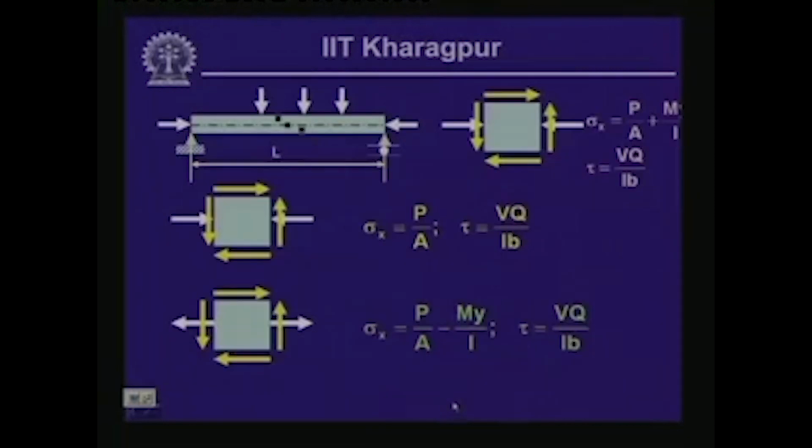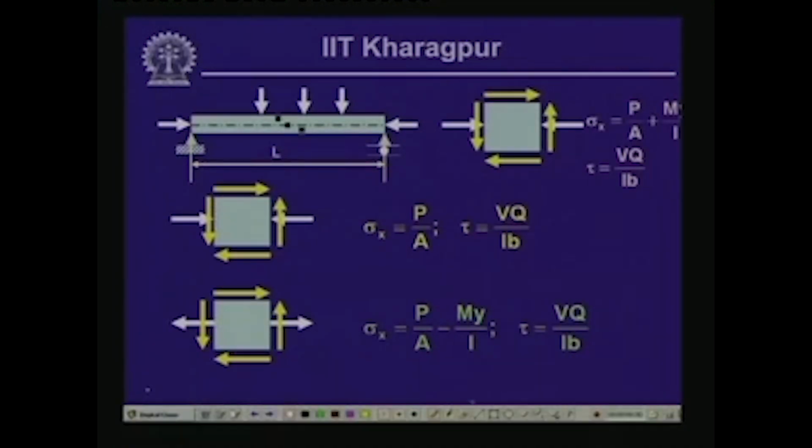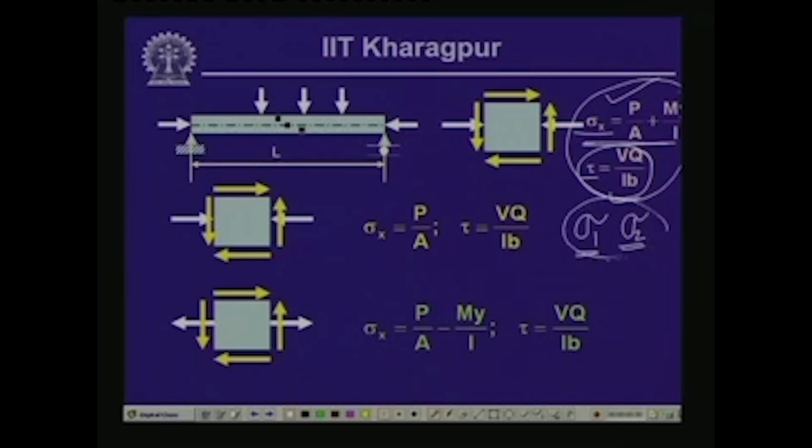Now, using this, if we would like to calculate the resulting stress, which we call the maximum value of the tensile or compressive stress, which is the principal stress, maximum or minimum value, that we compute from the Mohr circle, and this is what has been done over here, that we can have this kind of relationship. That means this is for the normal stress and this is for the shearing stress, and based on this normal stress and shear stress we can compute the value of the maximum principal stress sigma 1 or the minimum stress sigma 2. These are the principal stresses, and also we can compute the value of the in-plane shear stresses, that is, the maximum value of the shearing stress that will be occurring at any point.